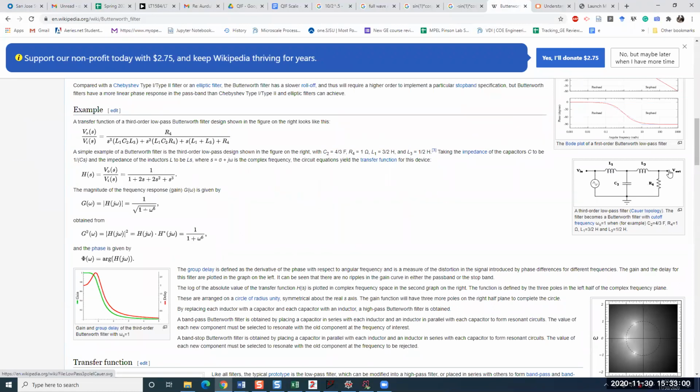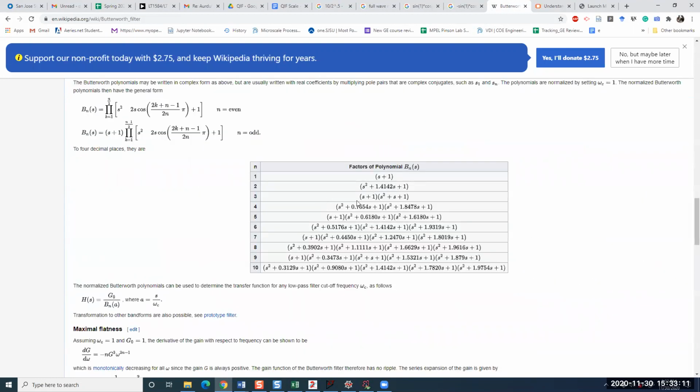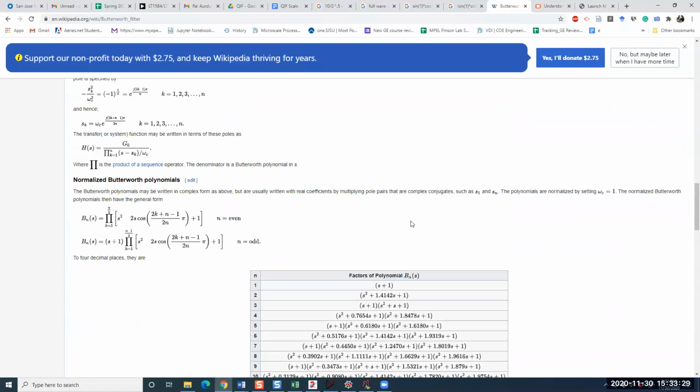Sure, I would put an op amp with a buffer on the output here, because if you connect anything to this it's going to throw everything off. But they've got the constants already broken up into first and second order equations so that you could use RLC or multiple feedback or Sallen-Key building blocks. They've already kind of done the work.